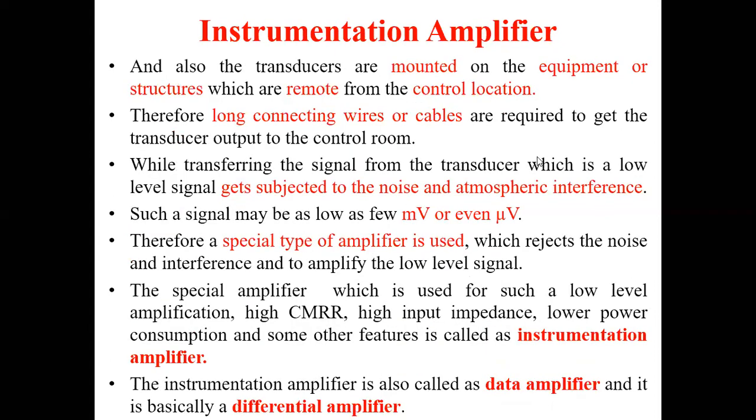At the same time, the transducers we are talking about are not near the control room. They are mounted on the equipment, far away from the control room. For example, take a thermal power plant. In a thermal power plant, we have boilers, which are at most half a kilometer from the control room. On these boilers, temperature sensors and pressure sensors are mounted.